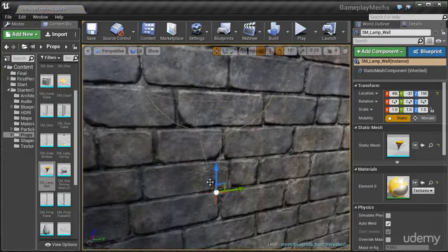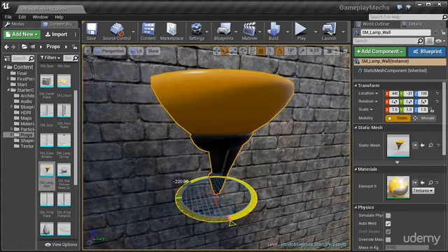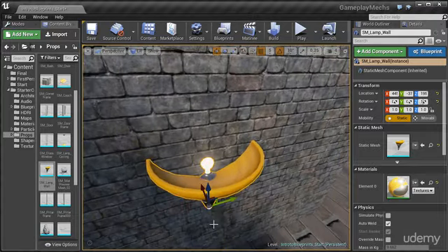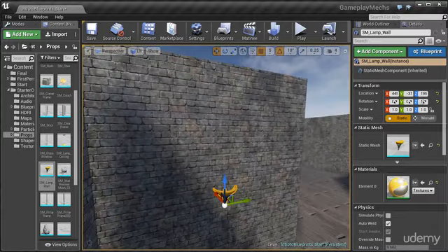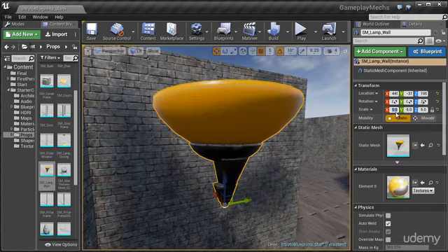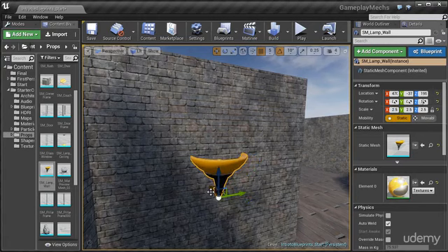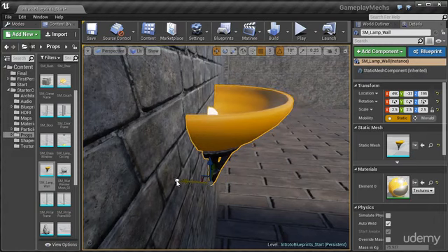come over here, push F2, and if you hold shift it will move with that object, and we're going to just rotate that 180 degrees. Now this is actually quite small. I want that for this demo a lot bigger, so I'm going to click this lock button here so it scales uniformly, and then I'm just going to change that to 5. Okay, that's too big. 2.5. There we go. And then just make sure that that is put to the wall.